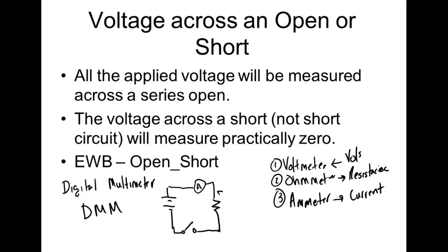So we had a device. It was a transmitter for an overhead for a crane, and it had a fuse in it. And if you tried to measure with an ohm meter, it blew a fuse. So that was a situation. It took us a little while to figure that out, by the way. So we blew a lot of fuses. So we had to figure out another way to check if the fuse was good or bad.